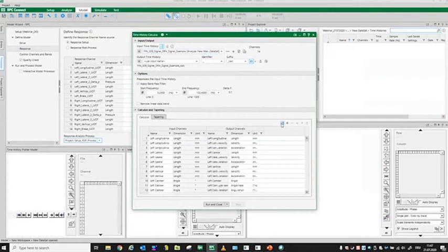So if I click on the time history calculus and include, as I understood your question, length, velocity, and so on, I am able now to choose whatever unit I want to have, like centimeters here for the velocity, here for the lateral, I want to have meters per hour. And for the vertical acceleration, I want to have it in, let's see, feet per second squared. So this can be available. This is no problem. You just hit run and close, and it will create the units you set here directly.